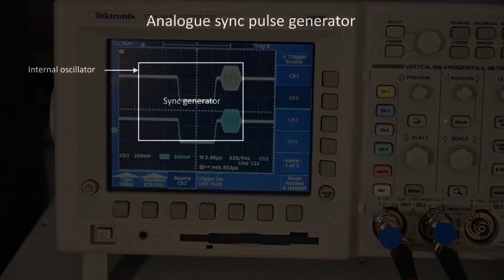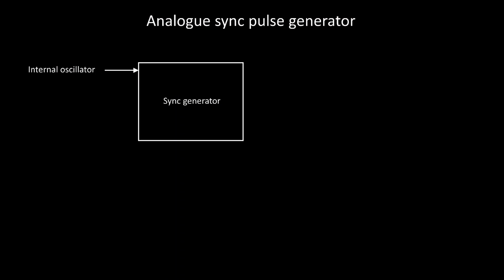The very first requirement of an SPG is some kind of stable frequency reference, and there certainly are a few options. Virtually all SPGs have an internal frequency reference, and this may be anything from a synchronous electric motor to a high stability oven-controlled crystal oscillator. In addition to this, an SPG will have a number of external reference options which will vary depending on the vintage and the requirements. Synchronizing with the electricity grid was one of the earliest frequency references, but with the obvious drawback that the frequency tends to vary depending on the load placed upon the electricity grid.